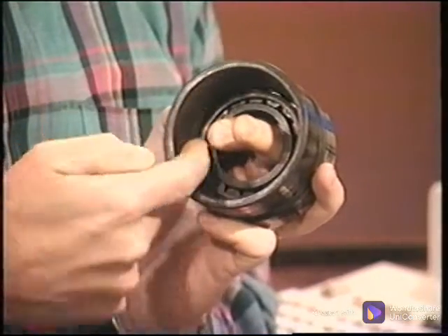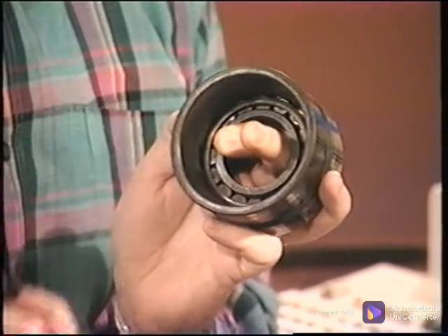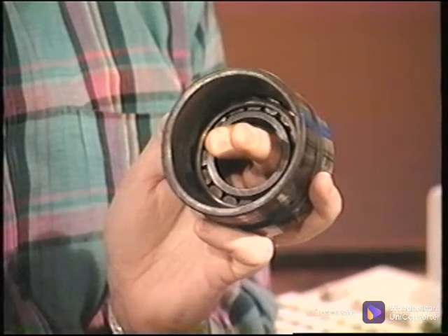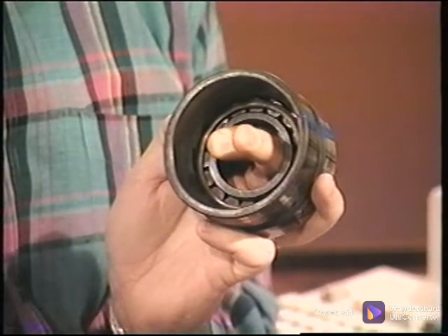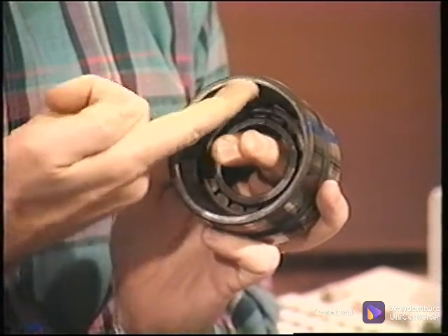One question often asked is, when entering data for double row bearings, do you use the total number of rolling elements or just the number per row? Let's take a look at this double roll bearing and determine the answer. If there is a chip out of one side of this outer race, there will only be one row of rollers passing through the defect. Therefore, the frequency should be calculated based on the number of rolling elements in one row.